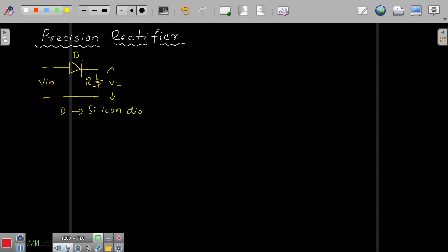it has a special representation here. When I speak about the silicon diode, you know that all the diodes are either silicon or germanium based diodes, right? So now the very conventional operation of this diode or this rectifier, you know, is that whenever the input voltage V in goes above the threshold voltage, which is generally 0.7 volts in this particular case, the input itself is represented at the output, right?